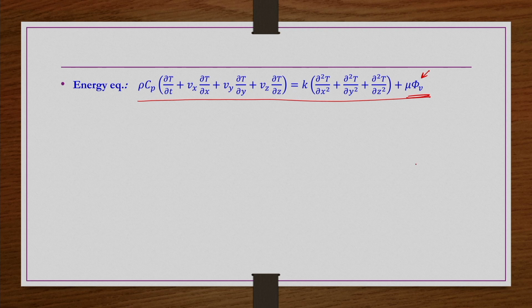In general, when you write the energy equation, we take only the temporal term, the convection term, and the conduction terms. Other terms, such as reaction terms and viscous dissipation, are written only if they are specific to the problem; otherwise we do not write them. So, now specific to this problem, the viscous dissipation term should be included.